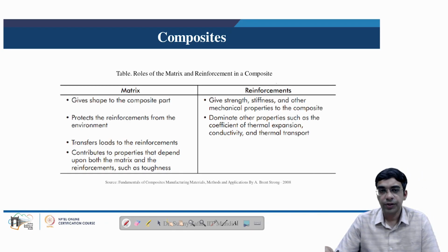So in any composite which is used, there are primarily two parts, the matrix and the reinforcement. Both components have their own specific roles. The matrix, as we know from the discussion on engineering materials, can be either polymer based, metal based, or ceramic based. But for the application in wind turbine blades, it is the polymer based matrix, having low density and high specific strength and stiffness, that is widely used as the choice of material.